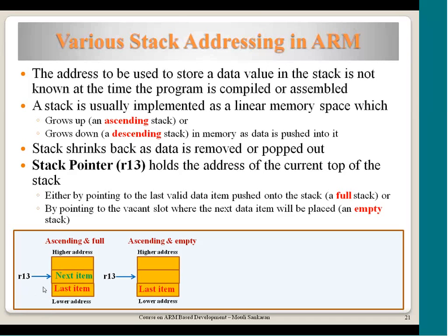So based on whether it is pointing at an empty location or the full location, the incrementing of R13 needs to be done anyway for every push operation. So whether it is incrementing or decrementing, it takes the same cycle as far as the architecture is concerned, but it is implementation specific and we can do it in any way.